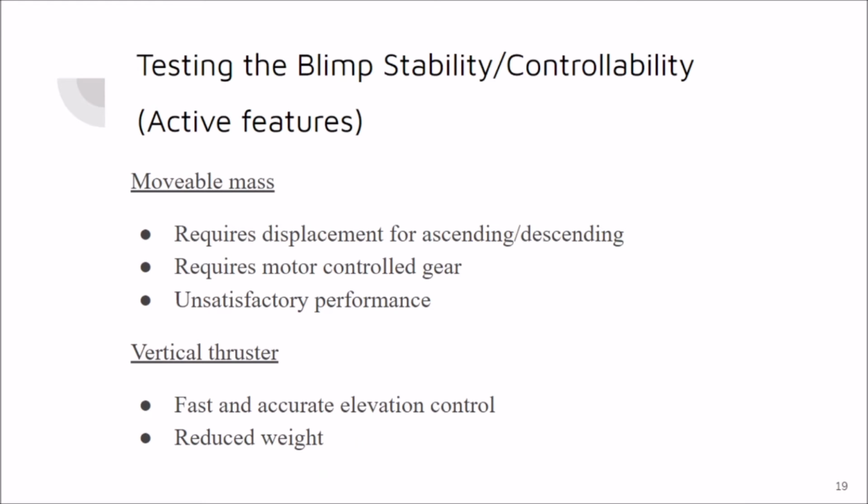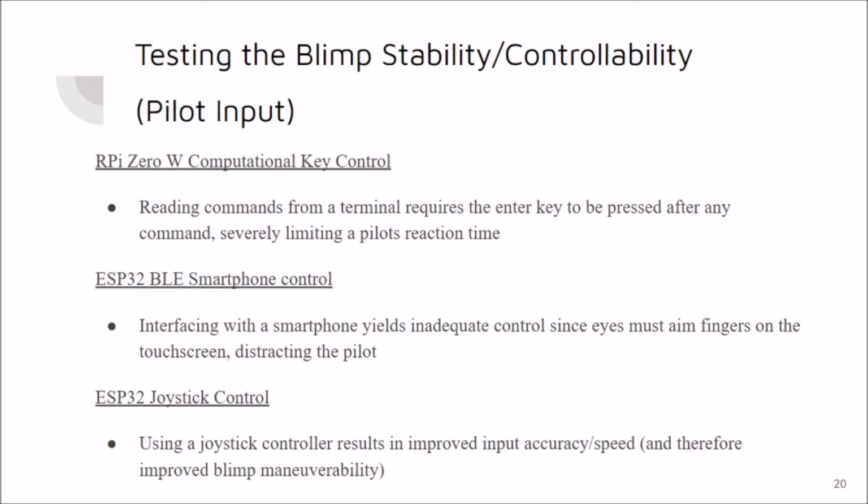This next experiment is about controlling altitude, which is a problem for pretty much all lighter-than-air vehicles. It's especially tricky. We started off with a movable mass feature to control the pitch angle of our vehicle, and then used the thruster to change altitude, but it was much easier to add a second thruster oriented vertically to control altitude this way.